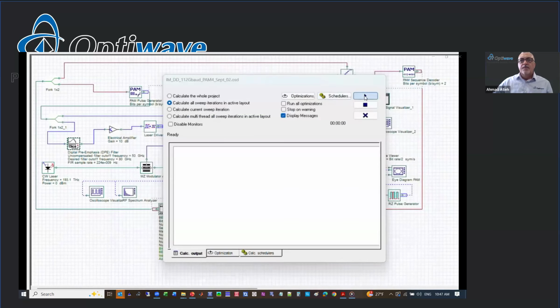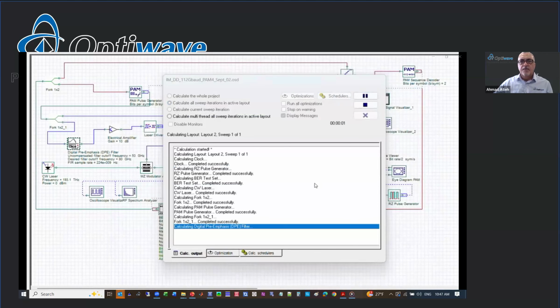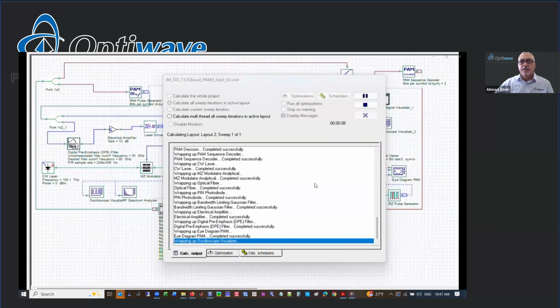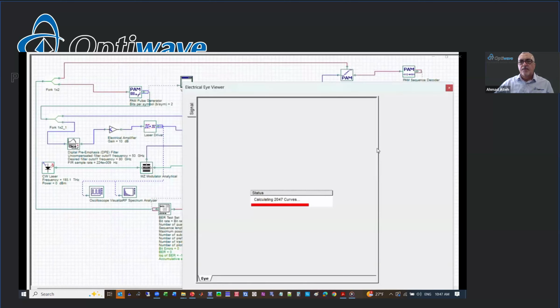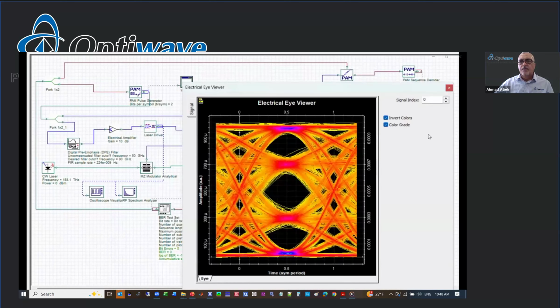And if we run this model here, we'll start now seeing a more reasonable and expected response, where the speed of the digital analog converter that will be implemented after the FIR filter coefficients and within the hardware limitations is actually consistent and reasonable. You can still see here we have error-free operation, and observing the eye diagram, it's fairly open.